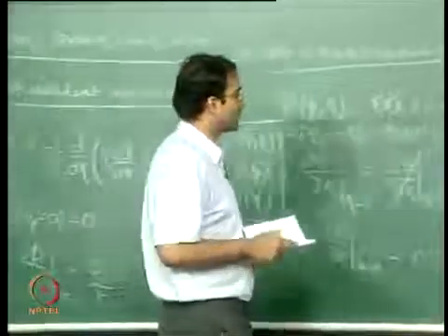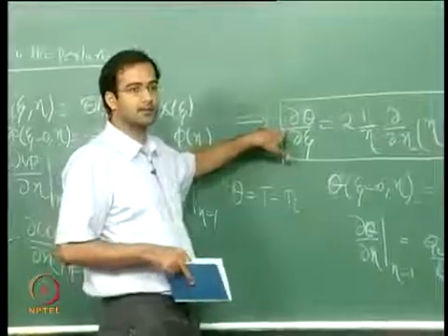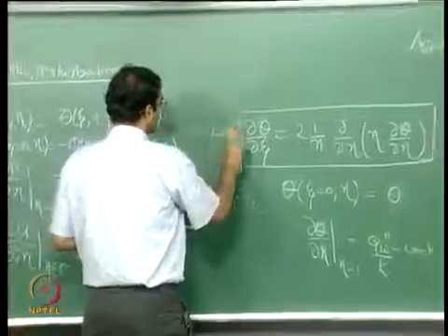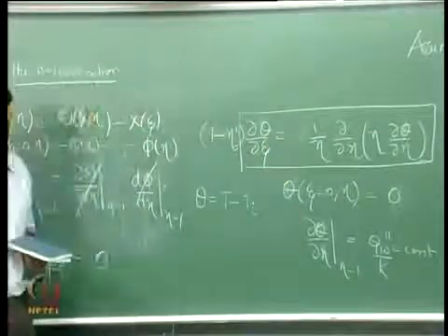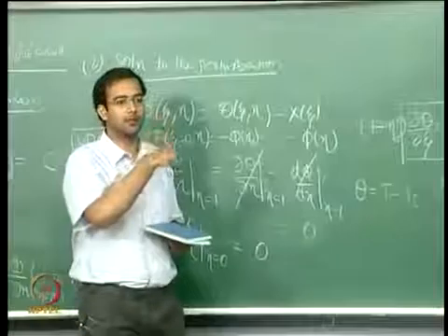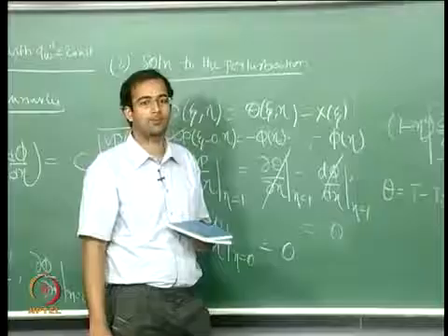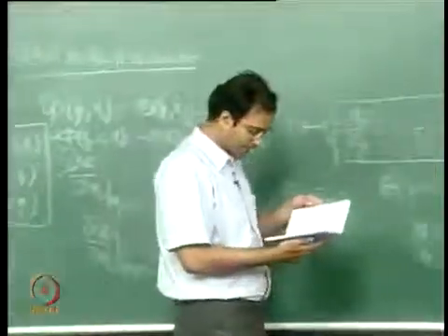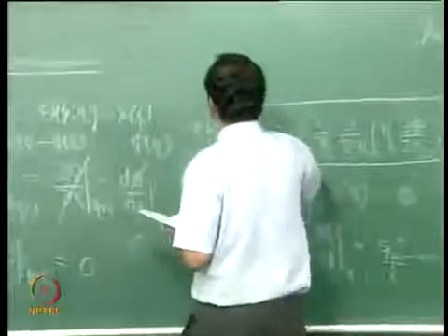In the case of parabolic flow, you have 1 minus eta square, which is coming here. When you substitute for the velocity profile, you have 1 minus eta square, and there is no 2 here. And therefore, the eigenvalue problem in this case will be what? Sturm-Liouville. Okay, the Sturm-Liouville kind of a problem. So Sellars did this, and the final solution for Nusselt number